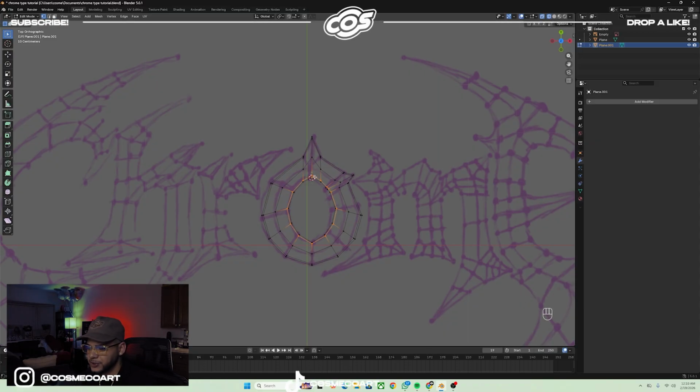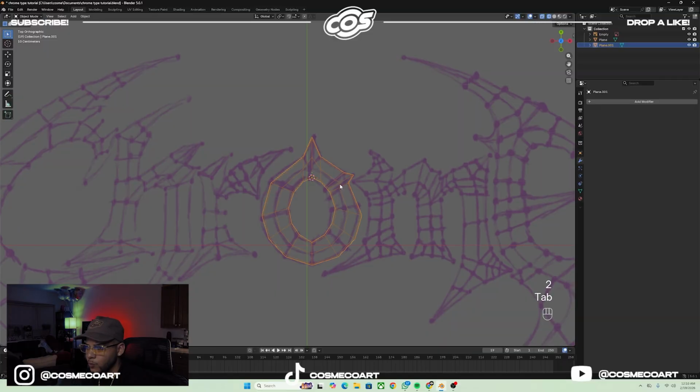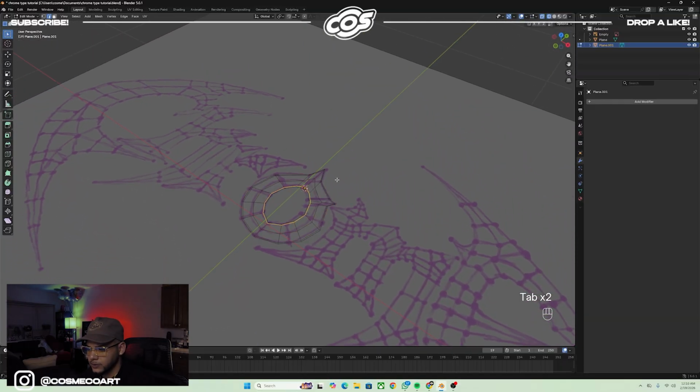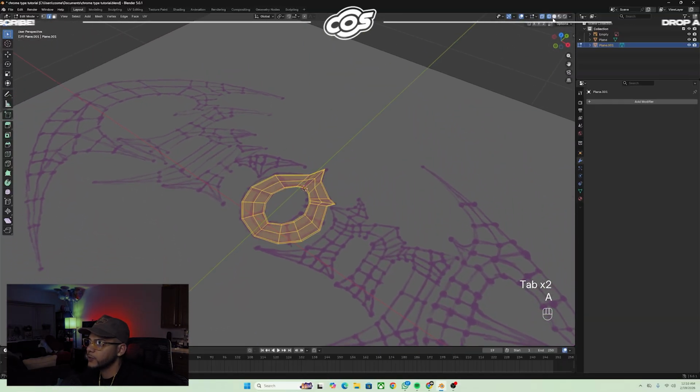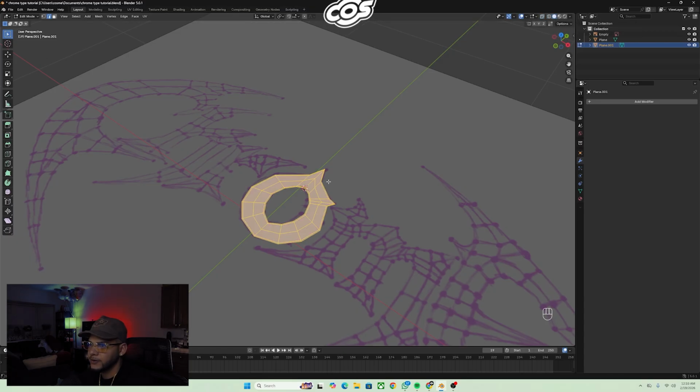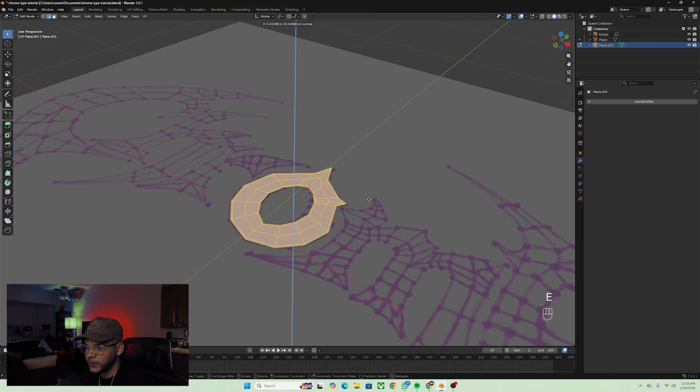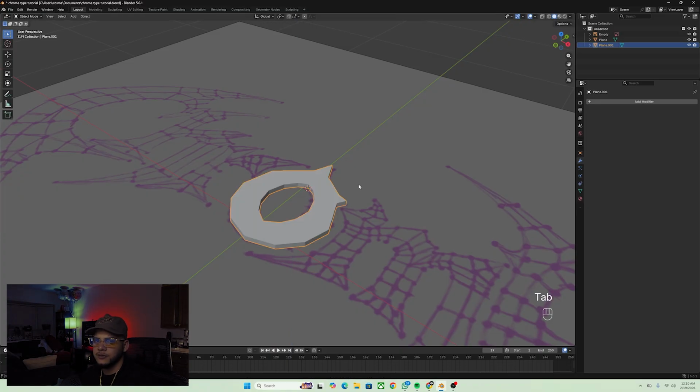Okay, now at this point, what's left to do is to select all of these. Let's go into the solid view mode and E to extrude, and we're gonna extrude it somewhere like this. Again, the thickness could be played with later on. So once you have all your text made up, you can play with the thickness so that the thickness of all of them lines up perfectly.